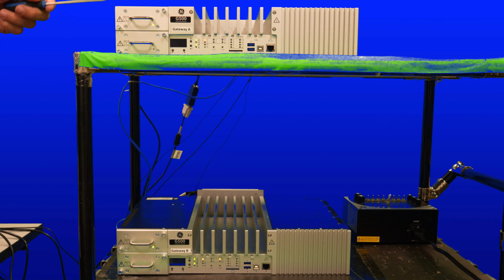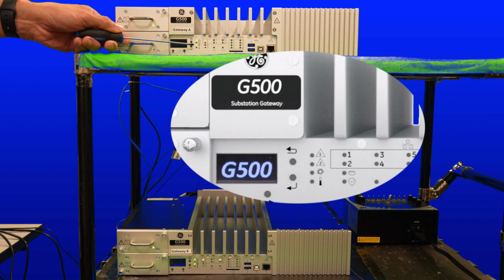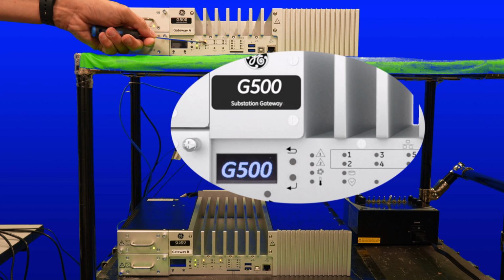This way, when it's rebooting, you know that the right one is restarting. Also, you've got to monitor these LEDs on the G500. I'll show you the monitor as we go through the steps of the setup. And what you will see is these LEDs, whether they're flashing or giving a certain color, that's in the document. Then you will know why your redundancy didn't work or what you did wrong during the setup of the redundancy. So it's a good indicator to keep an eye on. Also, it's a good indicator to keep an eye on your network activity.